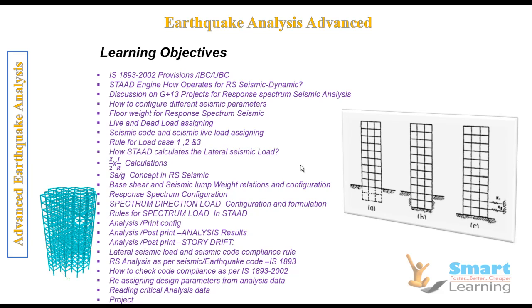Our learning objectives are the IS 1893 2002 provisions, different code compliance and its features. I'll also give you an overview of the STAAD engine and how it operates for response spectrum seismic analysis. Next we'll move to a G+13 structure and apply different concepts for assigning the response spectrum seismic design, and configure different seismic parameters, floor weight for response spectrum seismic, and live and dead load assigning.